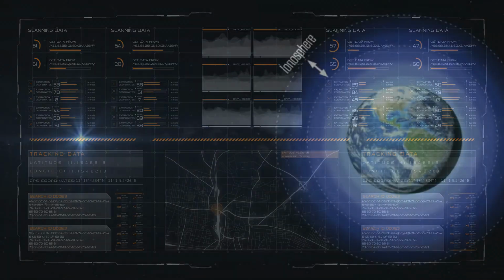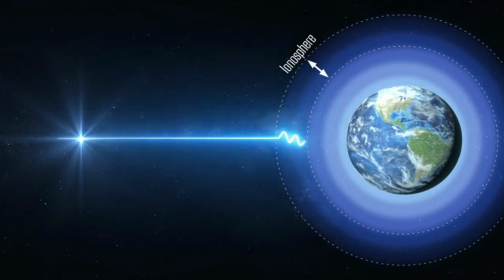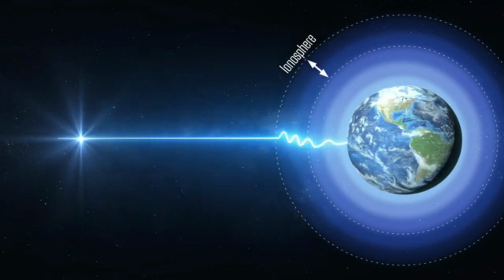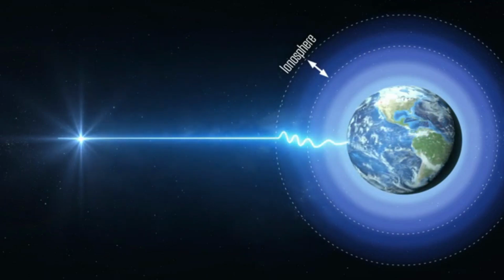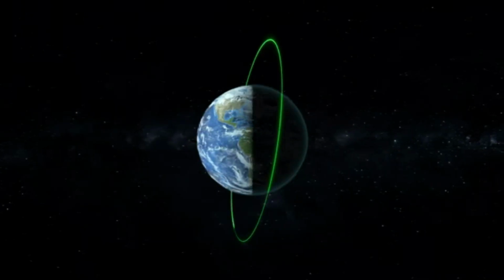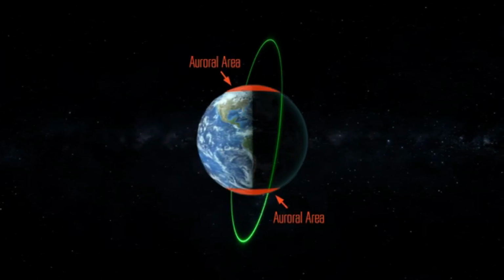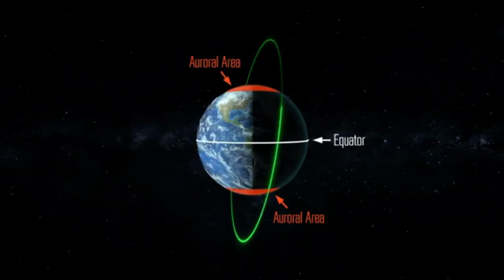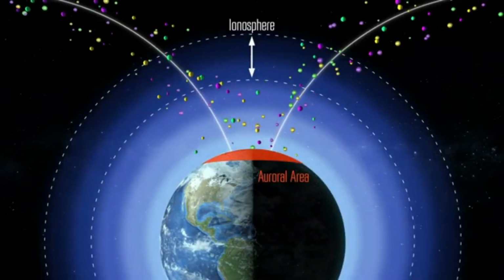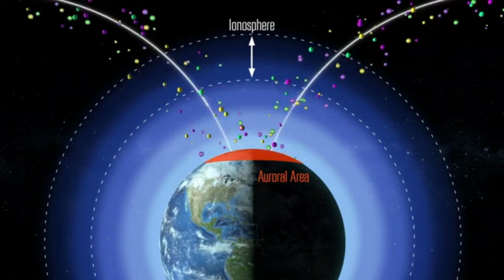To further enhance performance, the Adaptive Evolutionary Firefly Algorithm, or AEFA, is integrated into the control strategy. AEFA optimizes the fuzzy PID parameters by mimicking the behavior of fireflies, using their flashing patterns to find optimal solutions in complex search spaces. This ensures that the control system achieves the best possible balance between stability and responsiveness, even as the satellite encounters varying conditions in orbit.